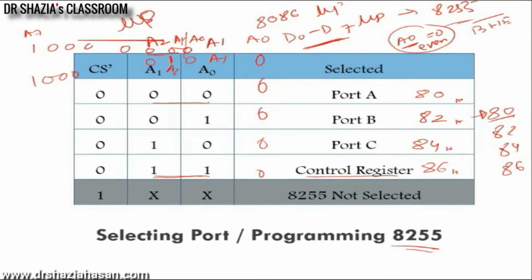Here we are not generating continuous addresses because you have connected an 8086 processor and we are using D0 to D7 of the microprocessor connected to 8255. Let us assume I have connected D8 to D15 of the 8086 processor to 8255. Then what should my base address be, even or odd? First of all, you have to tell the first address, the base address. Should it be even or odd? Odd. Let us assume I have my base address at 81H. Then what are the addresses generated?